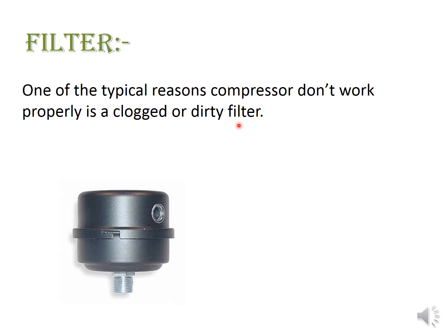The compressor will not work properly if you have a clogged or dirty filter. If you have a dirty filter, if it is clogged, the supply will be less and the compressor won't work properly. So you have to keep an eye on the filter. It is a must. You need to check the filter. Without a filter, the compressor won't work efficiently and it will get damaged very fast.